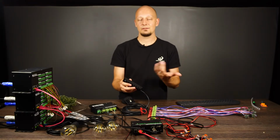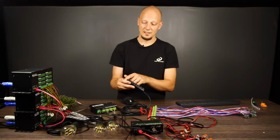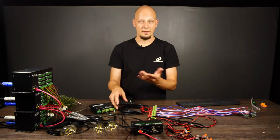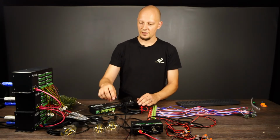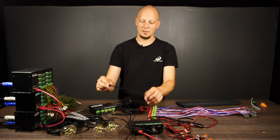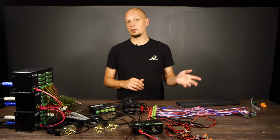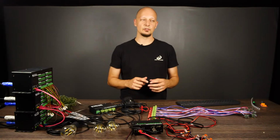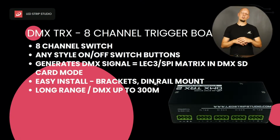The good thing also is that for these buttons, I used the standard, again, because we really like it, Cat6 cable, where I only used the 8 pairs that are available to connect these 8 buttons. And the advantage is that you can take it a very long distance, since it has twisted pairs and it's resistant to any noise that there might be along the way. So this is a very good option instead, for example, of a standard DMX cable XLR. Cat6 can be a very good option for you to send out the data. If you want to take it on a very, very long range, then DMX can work for up to 300 meters. So you can also use DMX cable.